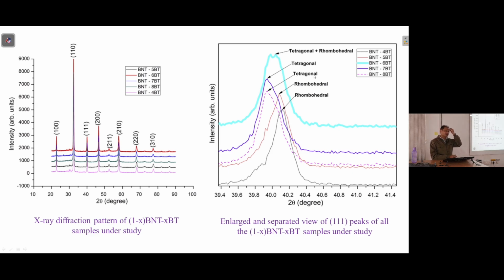Tetragonal of course is like when your cube becomes more like a rectangular parallelepiped, so that one side will be stretched, and for rhombohedral, like a rhombus. As you convert a square to a rhombus, its 3D version will become that a cube becomes a rhombohedron. So that kind of structure it is.